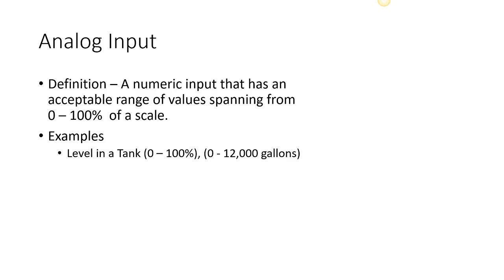that is in the tank. So it could go from 0 to 12,000 gallons in the tank. So there's our symbol of a process tank that we learned about in the last unit. And I'm showing a little sight glass right there in the middle. And that tank is right in the middle, so it's maybe a little less than 50%. So a low-level switch or a high-level switch, neither one would be active because we're in the middle.